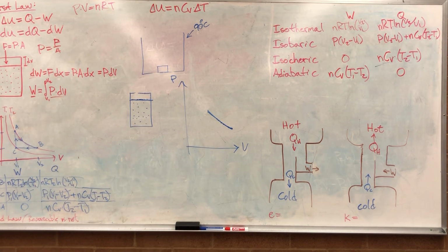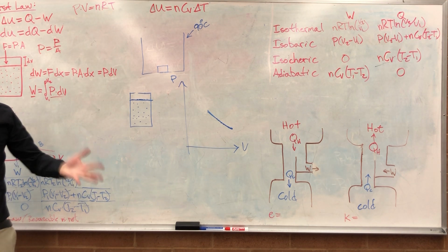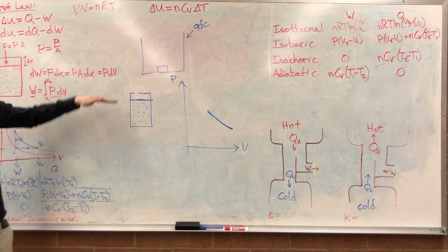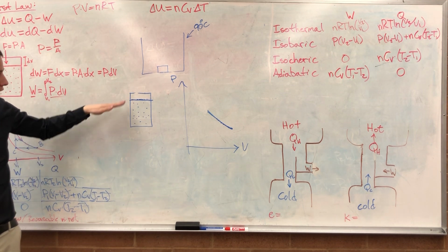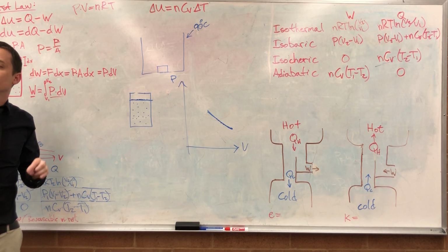So that's an example of reversible versus irreversible. If I move the piston with something big and sudden, that's not a reversible process. In general, reversible processes are ones that are slow, steady, keeping everything in thermal equilibrium as you go. No sudden changes.